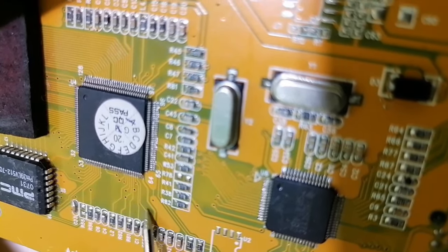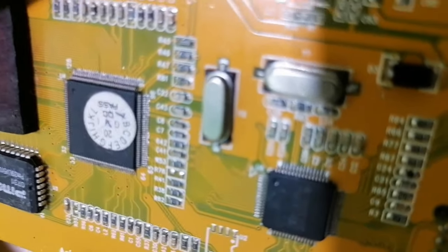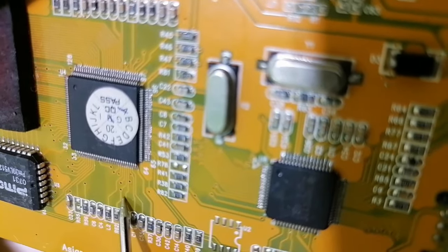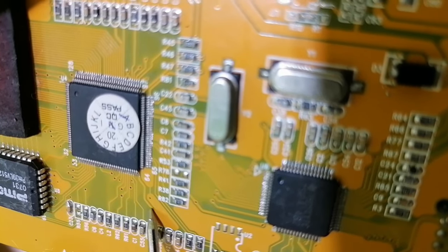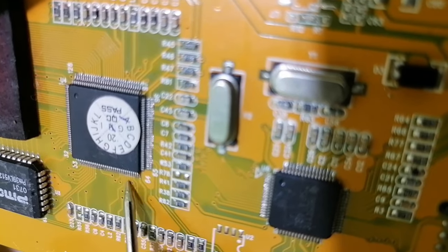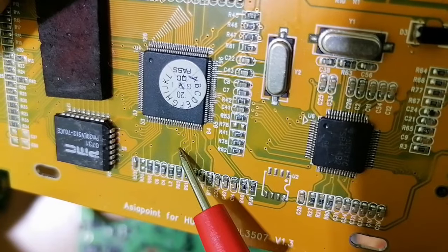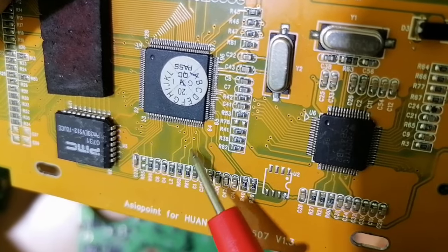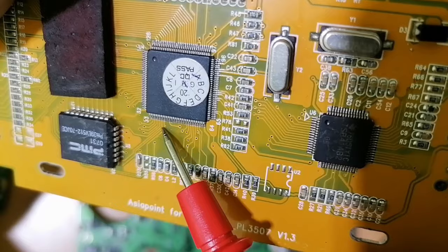So I want to share with you a very important tip. If you focus here, as you can see, we have these paths, these lines. Do you see? These lines are not the same as this one. This is a bolded line, and this bolded line means here we have power, VCC. And those lines, as you can see here, the thin lines, are just control signals.